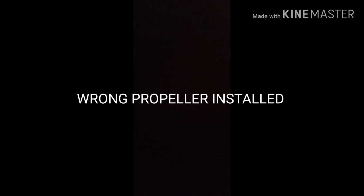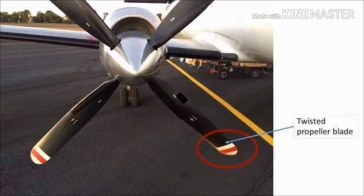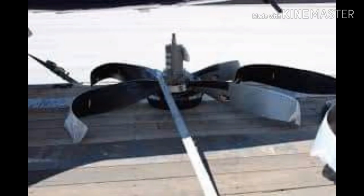A wrong propeller installed. An aircraft TCDS lists the engine and propeller combination for proper installation. The TCDS also lists the minimum static RPM for various combinations. An STC may have previously been approved to install a different engine or propeller on the aircraft, in which case the STC will list the minimum static RPM for a given engine and propeller combination.